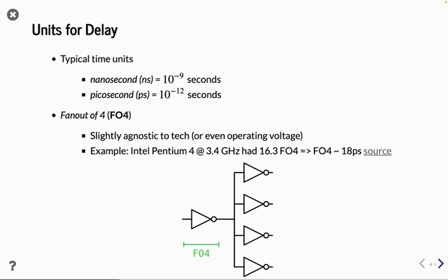So if you look at what happens within a given clock cycle, this one, and I'm pointing at my current laptop, is going through a lot more layers of logic, right? So it turns out this design is maybe about the lowest FO4 you have in the processor. This processor in front of me might be like a 20 or 30 FO4 design, which means it has much more logic it's going through. Because the transistors are faster, we don't necessarily see a lower clock rate or reduced clock frequency. That's kind of what's going on.